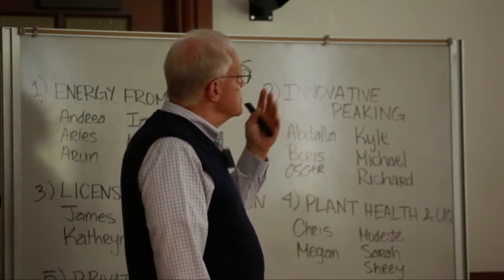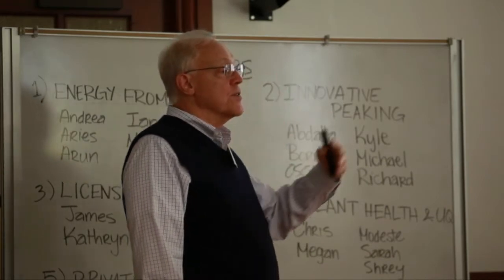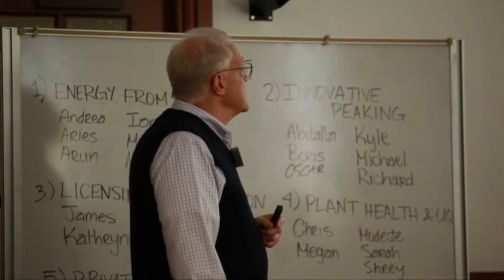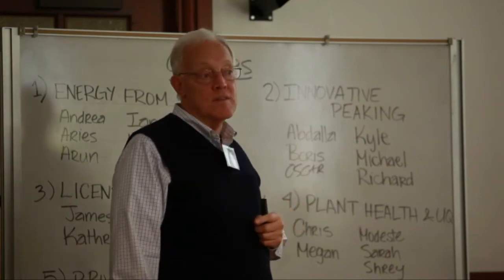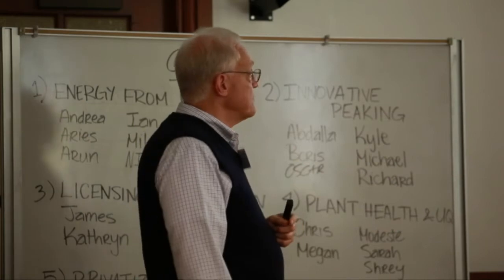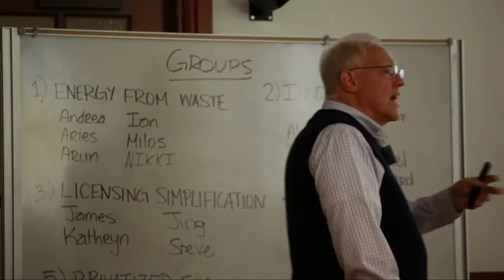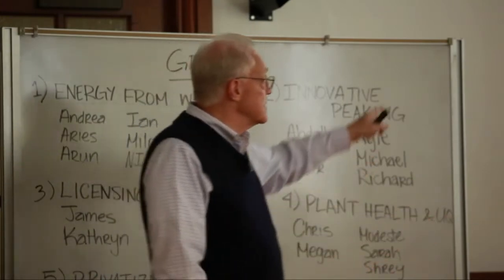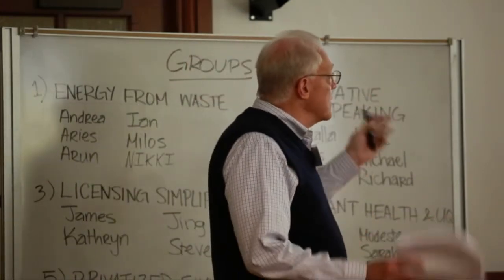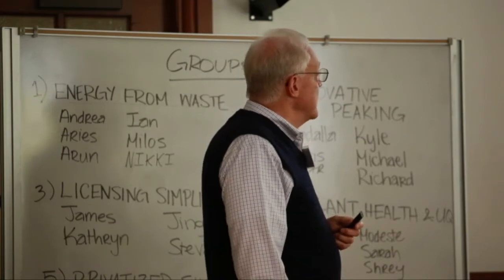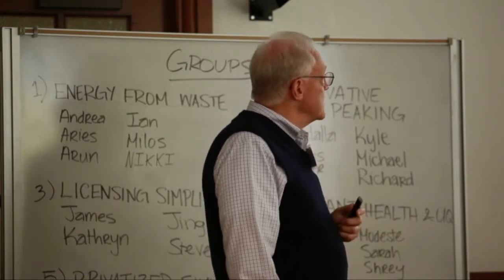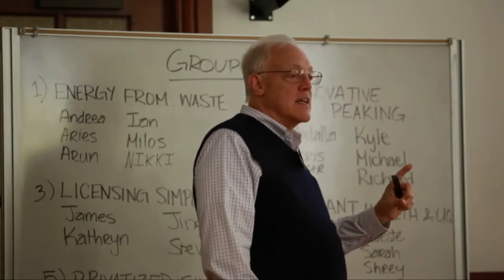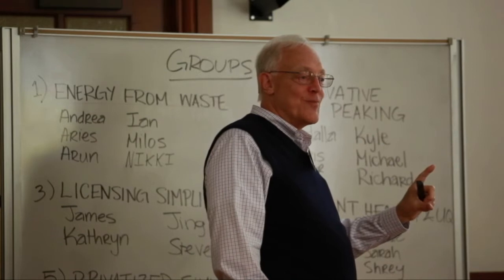Shippingport, which is the kind of technology transfer platform, had some zircaloy clad fuel rods, but most of it was plate type fuel. Which is now known, it wasn't known at the time, but today known, that's what the naval plants use, again, for structural purposes. Cooling water system chemistry differences. And I'm going to talk a little bit more in a few minutes about the PWRs and the use of boric acid. Naval plants don't use boric acid at all.